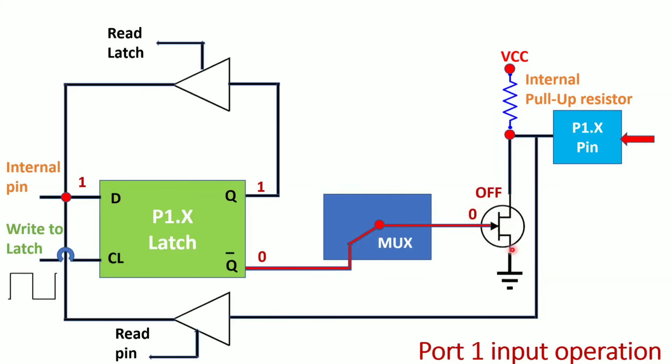Whenever the transistor is off, the internal pull-up resistor is connected to VCC and it is grounded, right? The current will pass from positive to negative here. Understood my point? Whenever we are getting this grounded, this stage is also known as the quasi bidirectional state. That means we don't get 0 here, and we don't get 1 here. That means almost 1, but we don't get 5 volts.